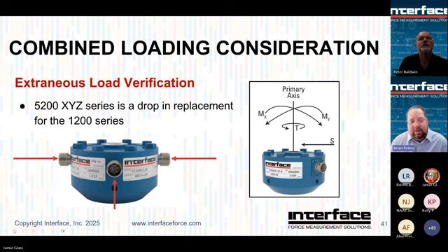And usually what customers are going to find is it wasn't a purely axial test. And guess what? There was a side load element to it. And that's why, if you think back to that S-sum equation we were looking at earlier, they were actually seeing more load than they thought and ended up breaking load cells. So again, we really, really recommend this unit. I don't think we sell as much as we should, just because it's always great to get more data. And it's really helpful for you to be able to confirm, are you seeing what you want?